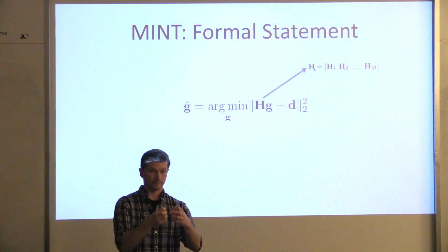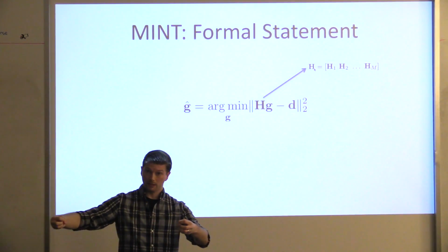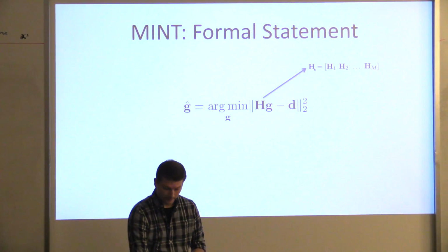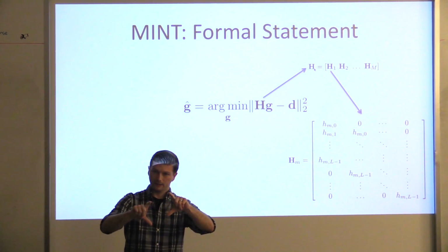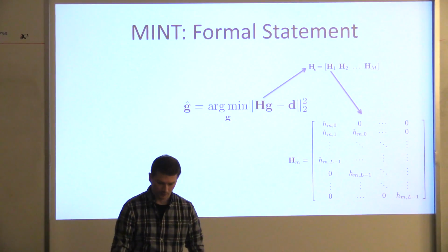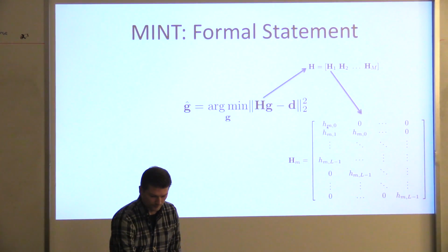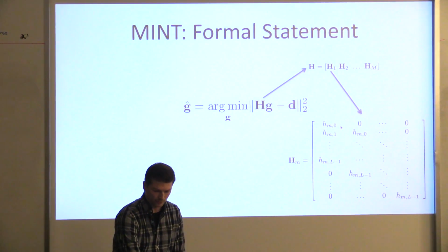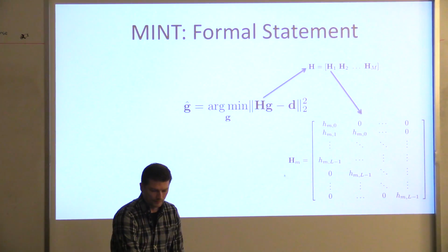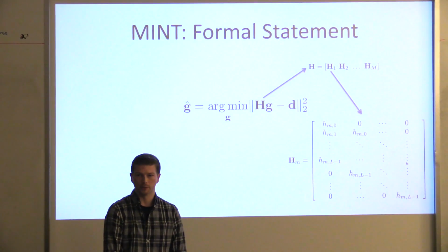The filtering matrix H is actually built up of lots of smaller filtering matrices. So what I've done is I've taken filtering matrices and stacked them across the horizontal axis. Each of the filtering matrices is just a shifted set of the original impulse response. So I've taken the filter H, the channel is M, and I just have to make the second subscript the tap index. And this is a convolution. This is the same thing that you get if you did conv MTX in MATLAB.